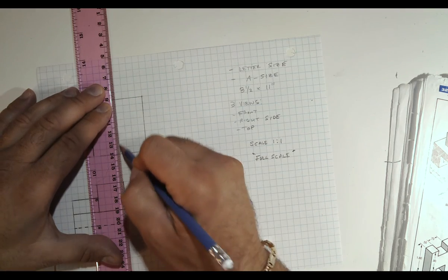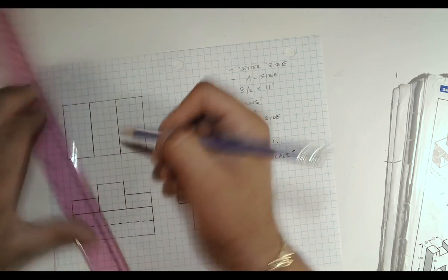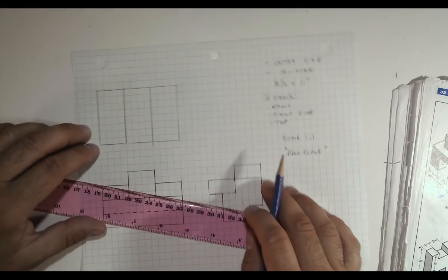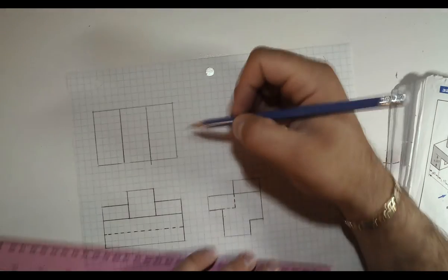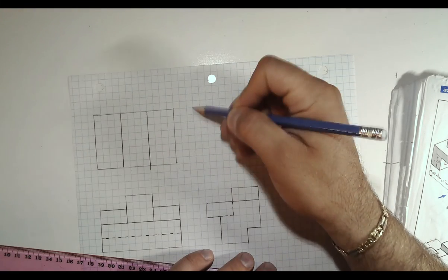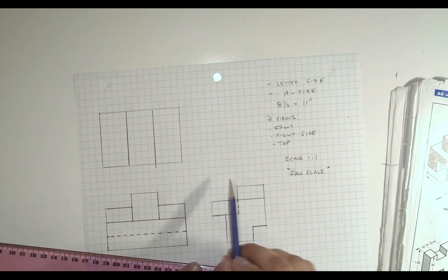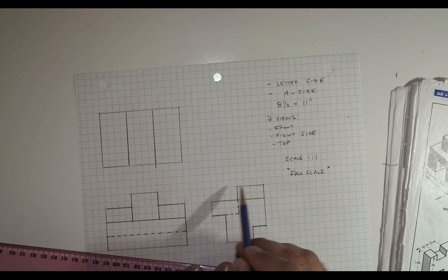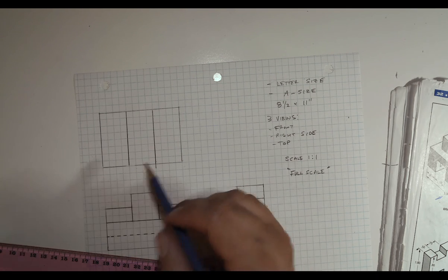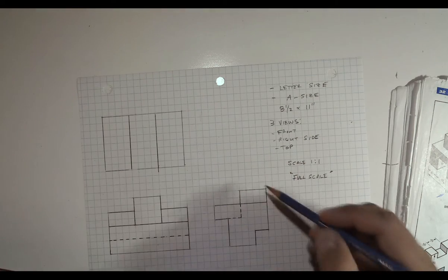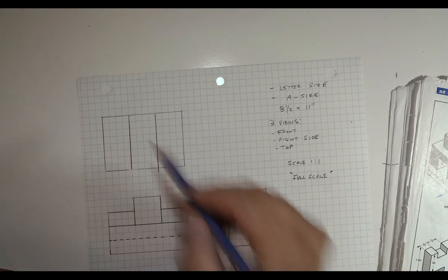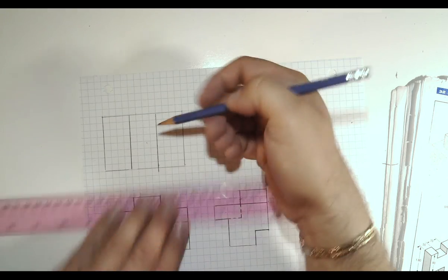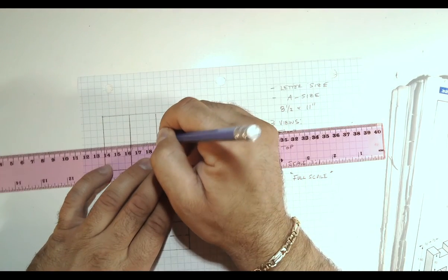I have these grid lines. So there are those features. Then there's this raised portion here. And again, this direction or this distance is depth. It's the same distance shown from left to right in the right side view. So these 4 grid spaces or grid lines represent 1 inch, which is the distance from the rear to where the feature ends. Rear, this is where the feature edge is. 4 grid spaces.